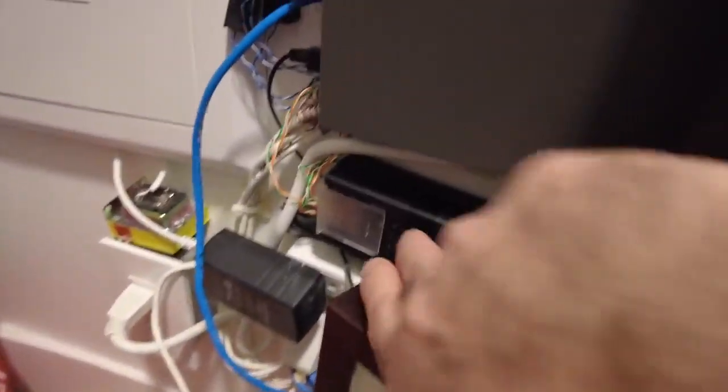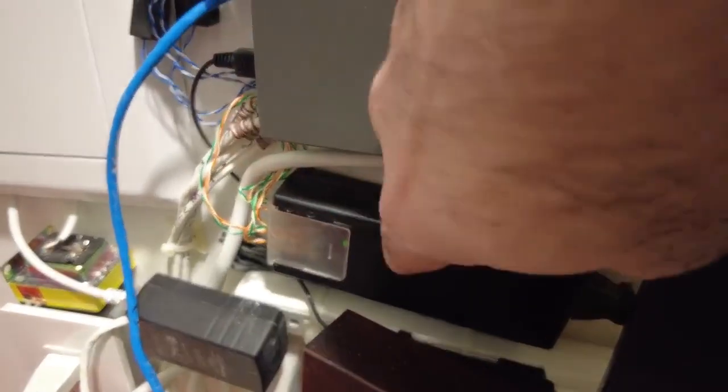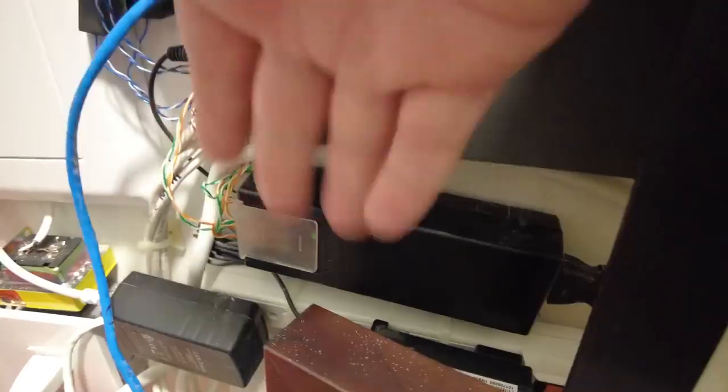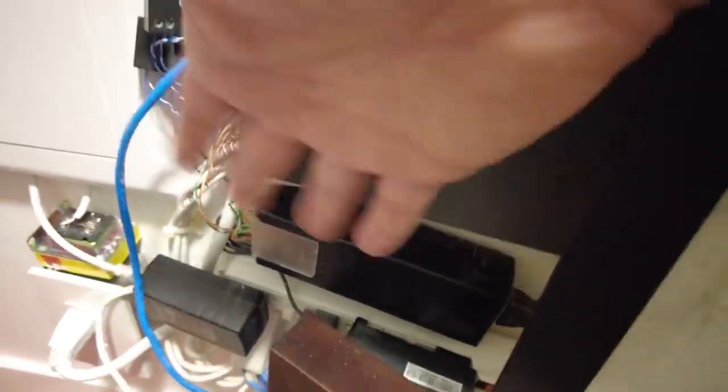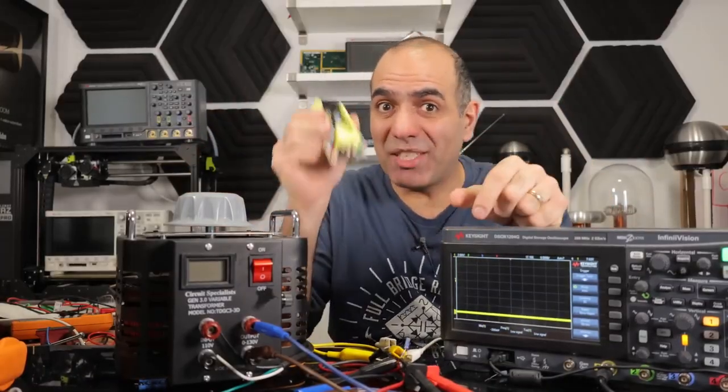Well, I did have a problem with this wall adapter here, which supplies all my security cameras, and all my cameras were turning on and off. I cut it open and lo and behold, it was a bulged capacitor. I replaced the capacitor with a higher rating capacitor and it's been working since. Now that we know all this, let's repair a broken power adapter together.